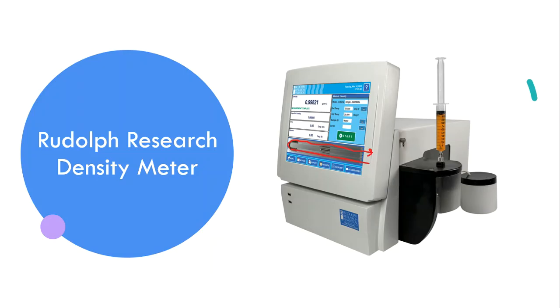So when we inject sample into the density meters, we want to make sure that we inject enough sample where a little bit starts to come out of the machine. It's always better to overfill it than to underfill it, and the overfilling is not going to cause a problem because there's a little waste jug back here in the back that's going to collect all of that trash that comes out of it. So it's always better to overfill for that reason. You're not going to hurt anything by doing that.